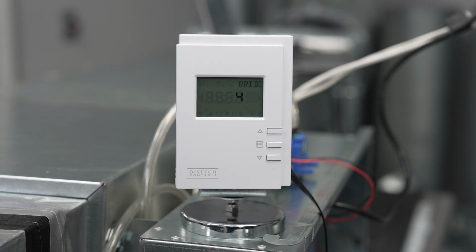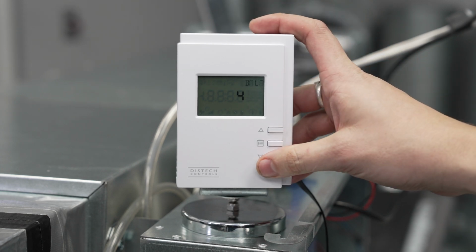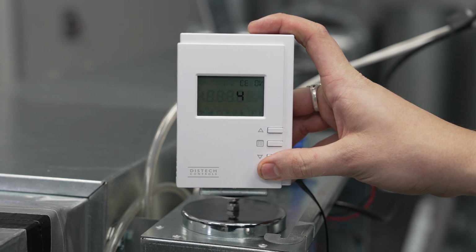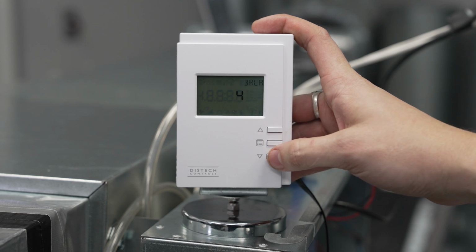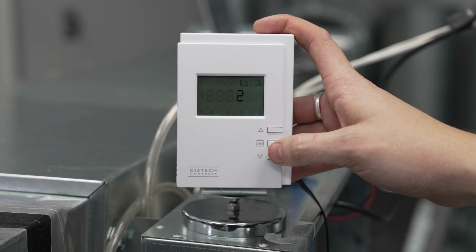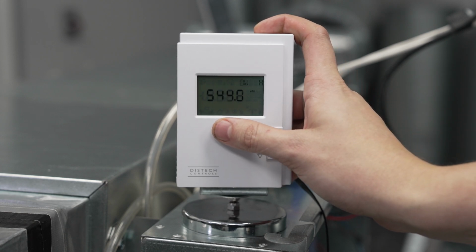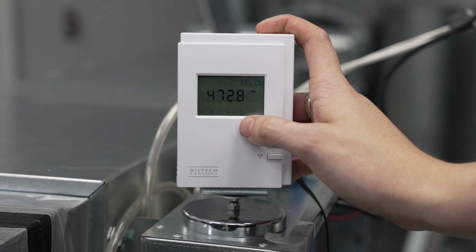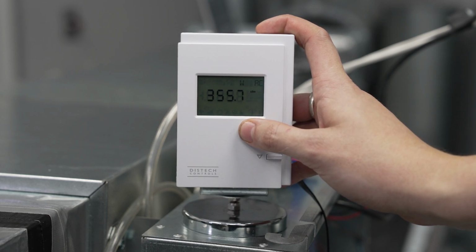Once your flows have been corrected at the max airflow volume, the next step for the SACV is to override it into its minimum airflow. Using the T-stat, we'll navigate the menus to get back to our balance mode override and select mode 2, which is minimum flow. After entering that command, we'll see that our flow begins decreasing to our minimum airflow set point. In this case, our minimum airflow set point is 50 CFM.